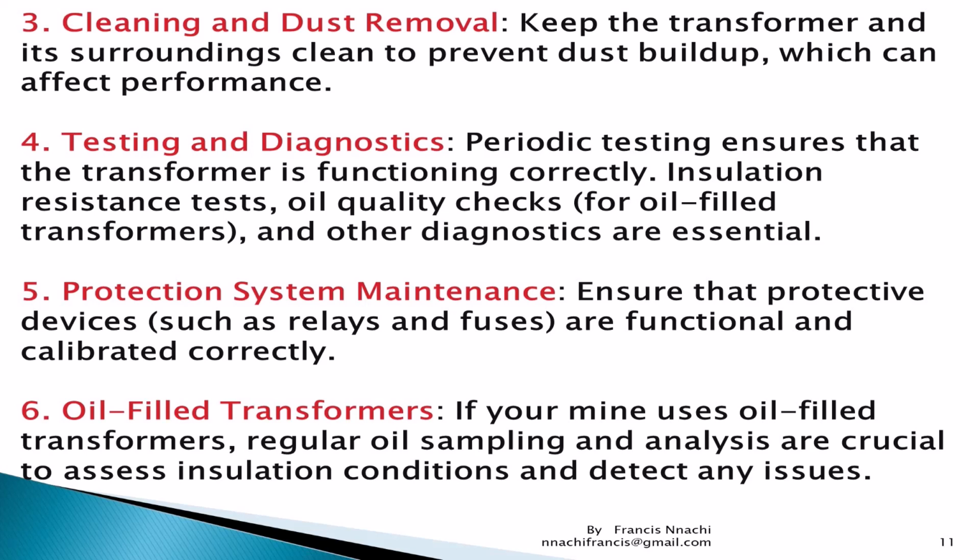All right. And then testing and diagnostics. There should be periodic testing which will ensure that the transformer is functioning correctly. Insulation resistance tests, oil quality checks for oil filled transformers, and the other diagnostics. They are very important. Now, protection system maintenance. You have to ensure that the protective devices, such as relays and fuses, are functional and calibrated correctly.